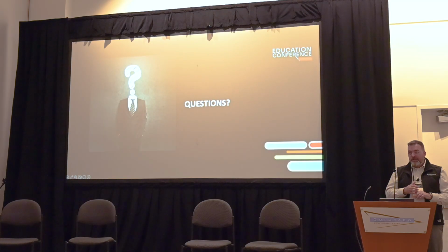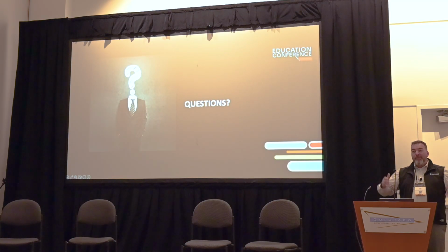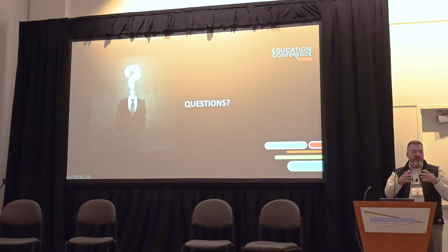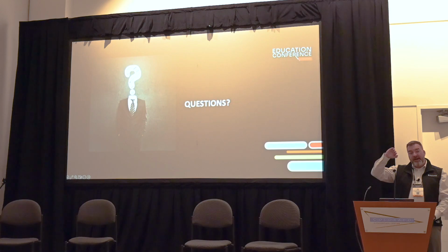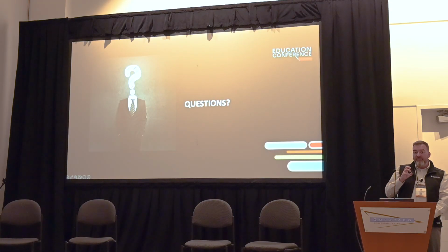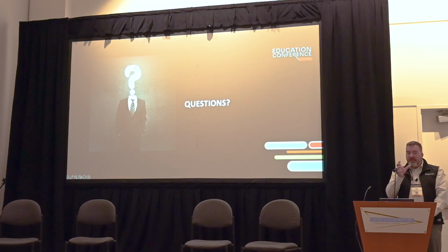but understanding how that goes together, you can layer those things. For example, 2700 Kelvin is higher in the red-orange spectrum. So typically things that are orange, buff-colored, sandstone, take that color light better. But green trees and things like that can get a little muddy. So if you shift up to like a 3000, you're going to have a higher green-blue spectrum in that LED, and it's going to reflect the light off of what's naturally in those objects much better, much cleaner. Even bumping up, if you want to have even more of an accent, think about conifers, maybe in a few areas as an accent or to draw your eye, maybe something like a 4000 Kelvin, and just pop that color a little bit more.